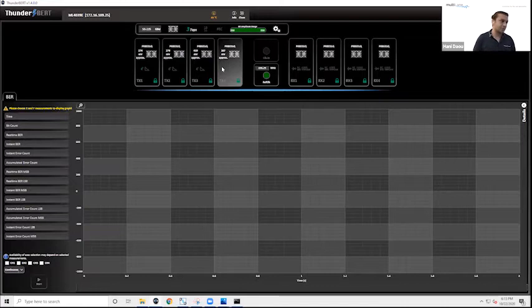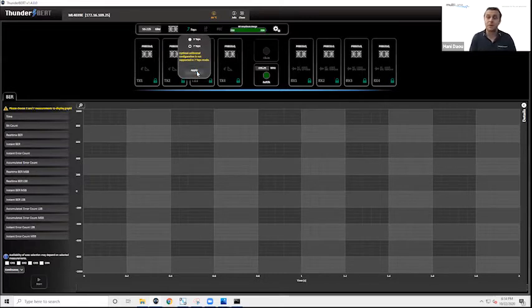Now, talking about power consumption, we have our equalizer set to the most power hungry setting, which is setting the equalizer in the transmitter to the full blast, if you will. Our BERT has either an optimal transmit mode where you can just set your output amplitude, a 3-tap transmitter mode, or a 7-tap transmitter mode where we use a 7-tap transmit equalizer to give you very, very fine control over the transmit signal. So not only can we use that 7-tap transmitter to give you the cleanest signal possible, we can also use it to corrupt the signal.